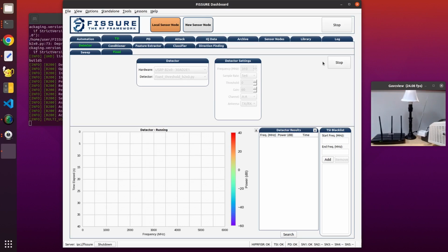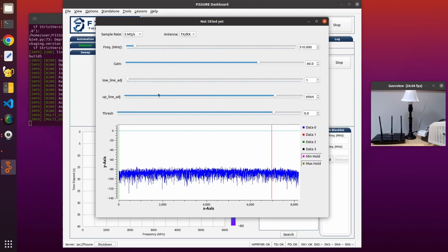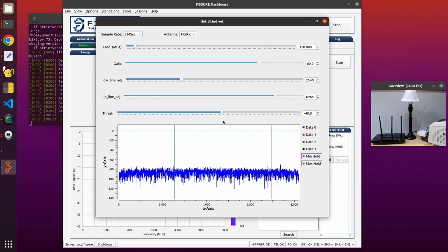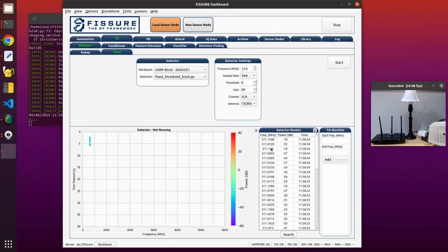this will sit on a constant frequency, and it copies the GNU radio tutorial example. So you can adjust your window that you're looking for, the threshold you're looking for. And then when I use this remote here, it's this guy again, I press the button and it'll show up over there. I think it hops around a little bit as I press each button. Hit stop, goes away. And what you're going to see here are a list of frequencies for that device. Now, if it's something that's hopping around, it's not going to be that useful. You'll see it plotted over here if it's running. But the point is just to find potential things to narrow your focus on.